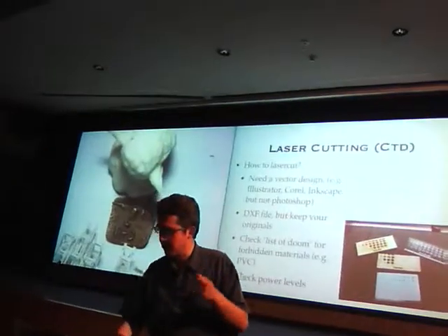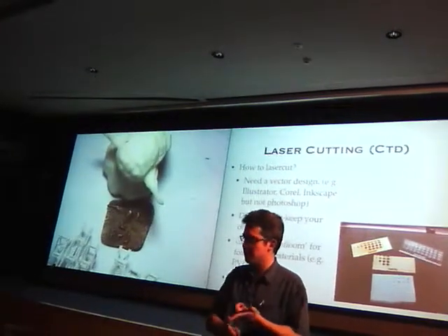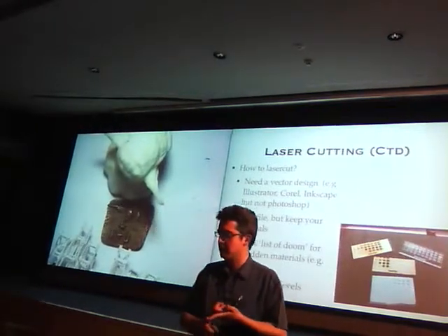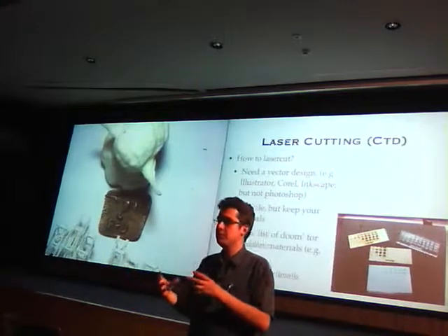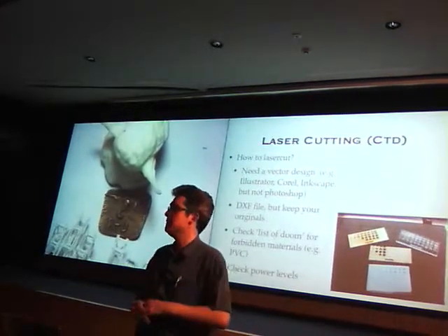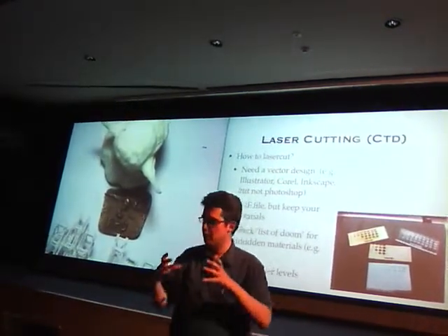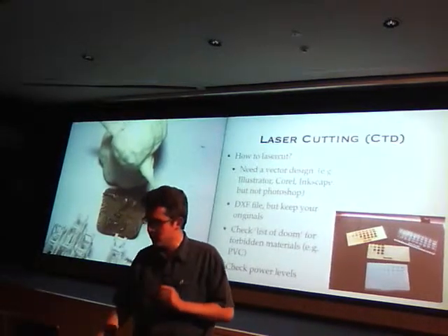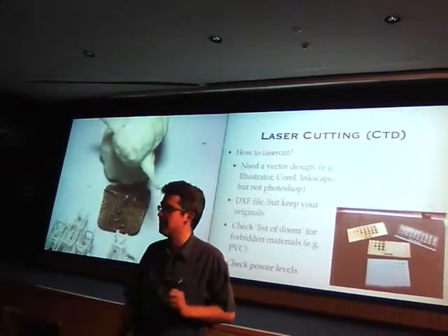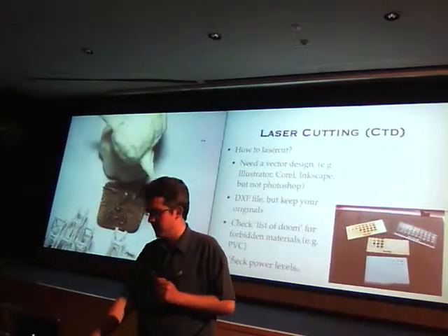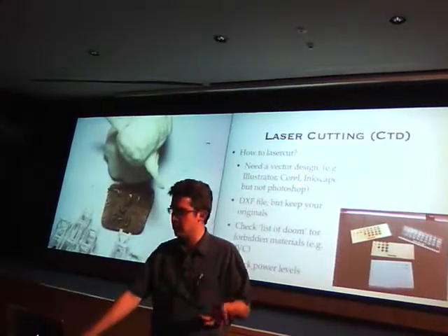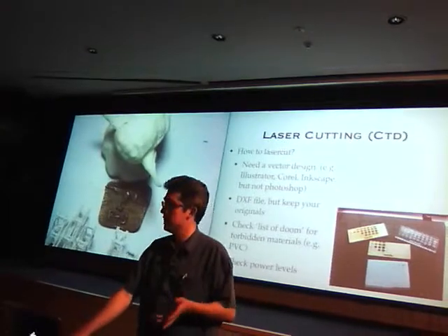How do you get into laser cutting? You need a vector design, so not a bitmap, e.g. Illustrator, Corel, Inkscape, not Photoshop. What you want is a DXF output to send to the laser cutter, but keep your originals because you may need to change stuff and recompile it later. We can't cut every material. There are certain plastics that will create chlorine gas and be bad for people and laser cutters alike, and power levels and stuff. Talk to me if you want to get into any laser cutting.